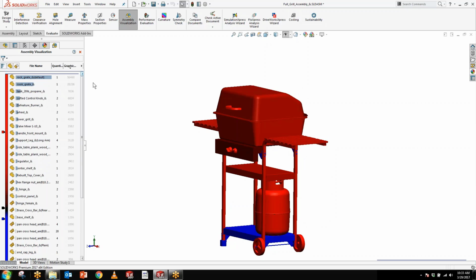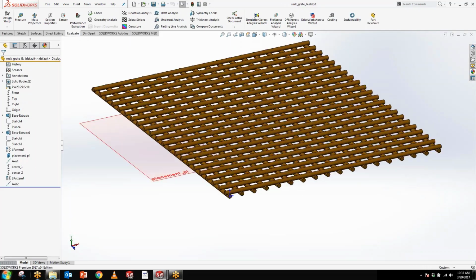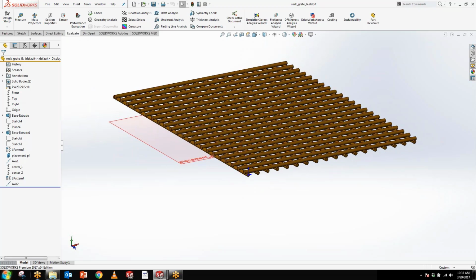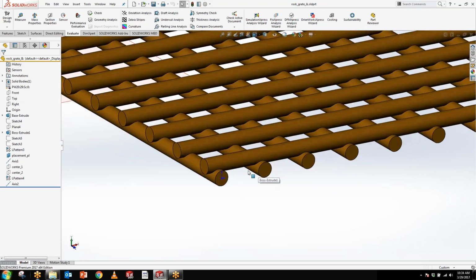And this is another big concern when it comes to big assemblies, guys. Sometimes assemblies with high details could result in some complicated graphics. So we might want to view which component is consuming the most out of those graphics. So let me go ahead and open up this part. Apparently this part was consuming a lot of graphics based on the graphics triangles that we sorted.